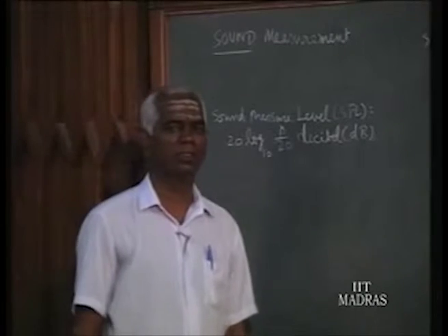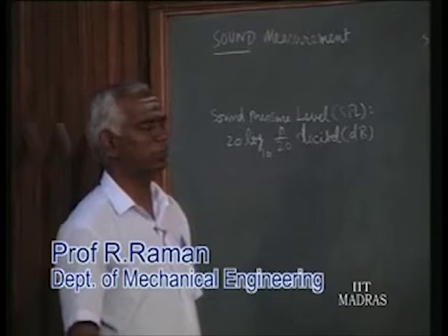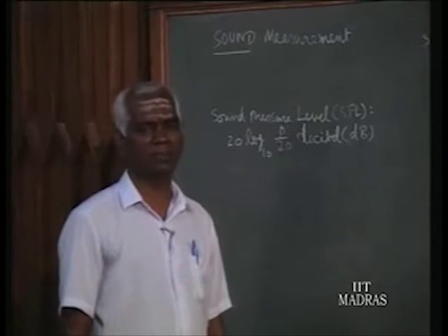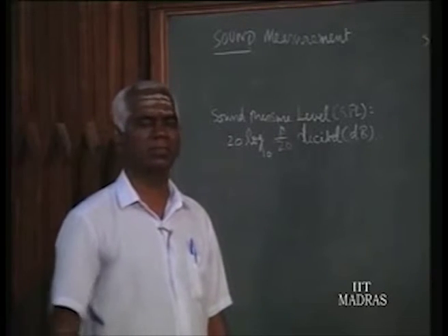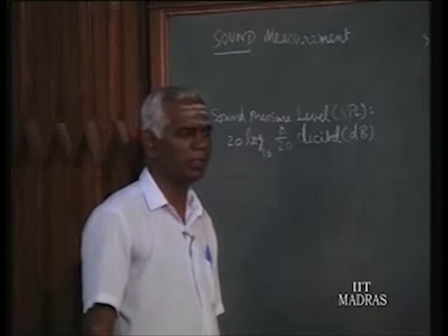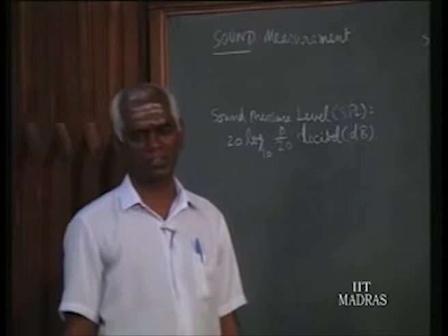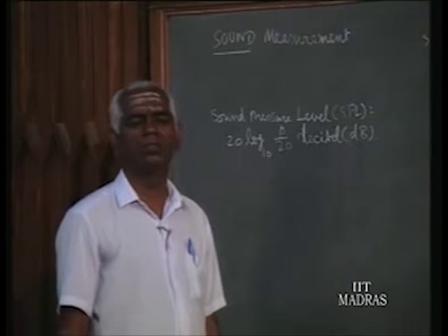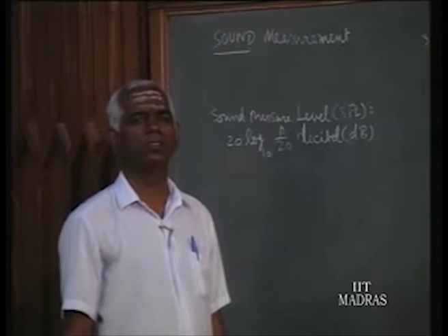We have seen until now pressure measurement and the vacuum measurement. Vacuum measurement, we know it is again a pressure, it is a lower pressure than atmospheric conditions. So we call it vacuum. So it's again a pressure measurement. Vacuum is pressure measurement. So whatever technique we used for the pressure measurement, we can use it for vacuum measurement also. For example, Bourdon gauge and bellows, diaphragms.